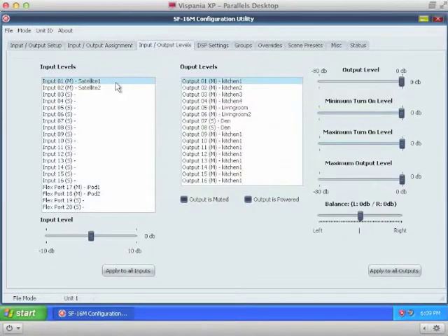The Levels tab allows adjustments to the input gain and output volume levels. It is best to trim the hotter input levels to match the volume of your other sources. Increasing the input gain can cause some distortion. Output levels provide a number of different settings.